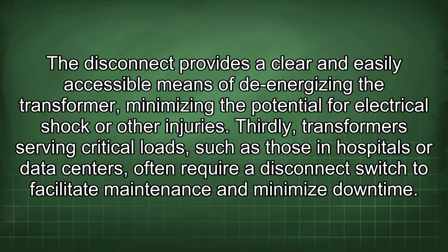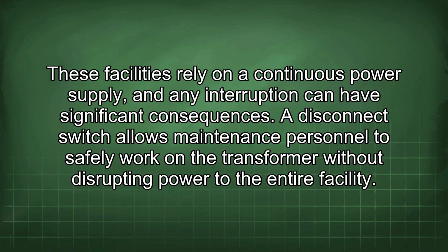Thirdly, transformers serving critical loads, such as those in hospitals or data centers, often require a disconnect switch to facilitate maintenance and minimize downtime. These facilities rely on a continuous power supply, and any interruption can have significant consequences. A disconnect switch allows maintenance personnel to safely work on the transformer without disrupting power to the entire facility.